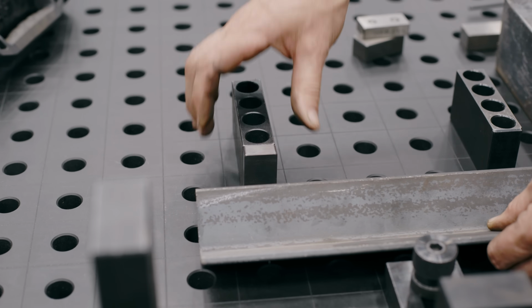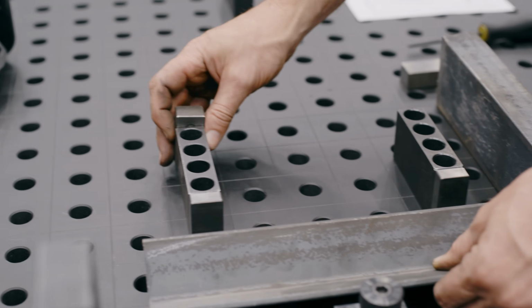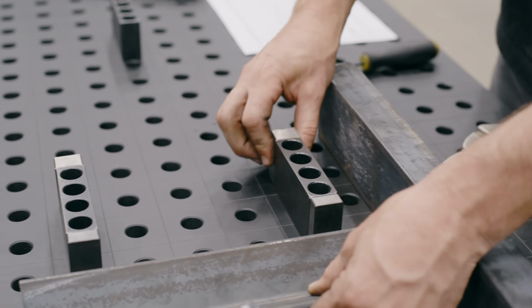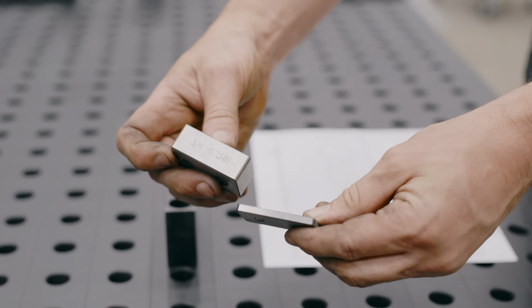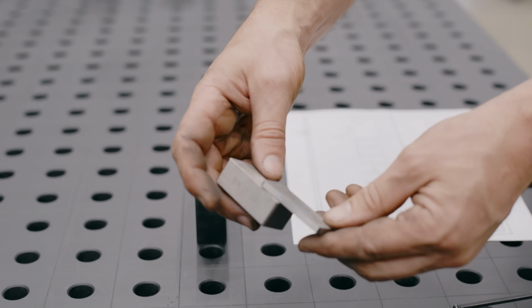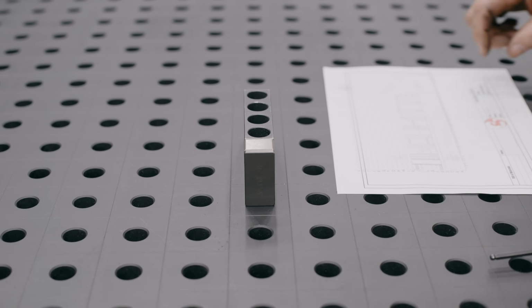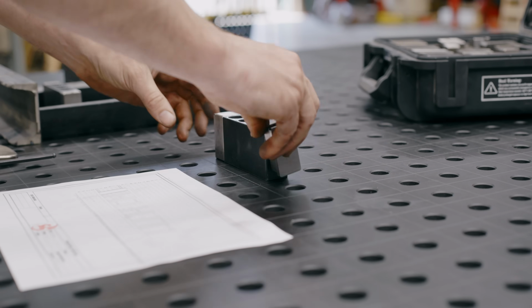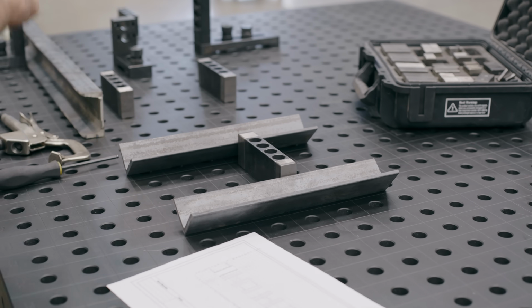We needed a 1/2-inch spacer, goes on the front, and then another spacer goes on the back. And that way you can have the correct spacing front and back in between. So for the next block, we need something like that. A 3/4, 3/16 would get us what we need for this next operation. We're just gonna treat it as such. It would look like that. And then we do on the other side, 11/16. That's how this setup would look if we just chose to do a 1.